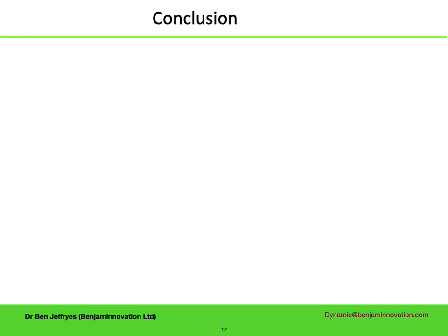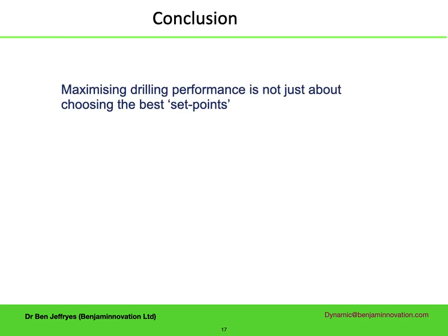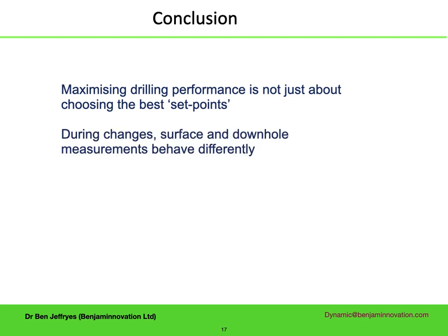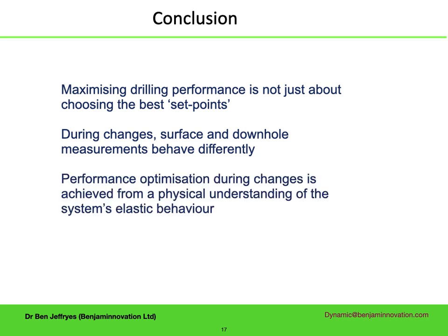Which brings us to the conclusions. Maximising drilling performance is not just about optimising set points. During changes, whether in drilling parameters or at the bit, surface and downhole measurements behave differently. Optimizing performance during these changes comes from physical understanding of the elastic behavior of the system.